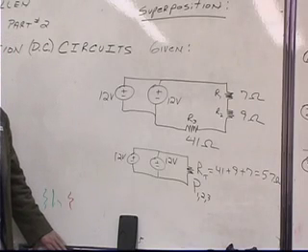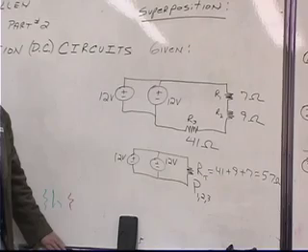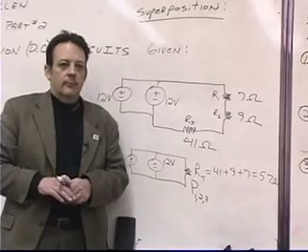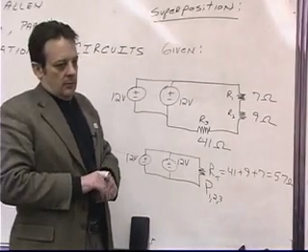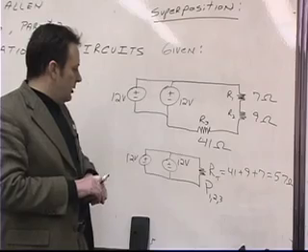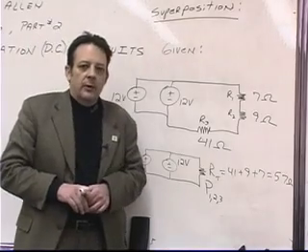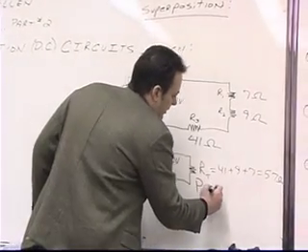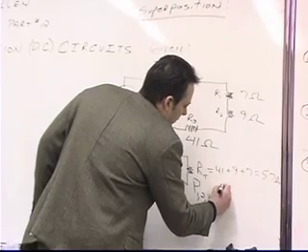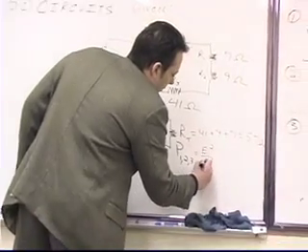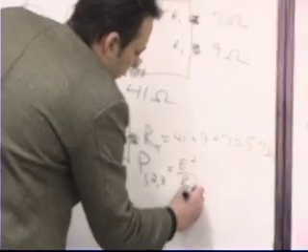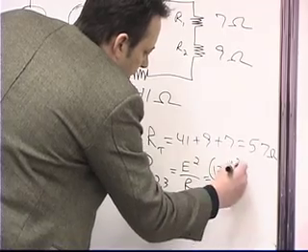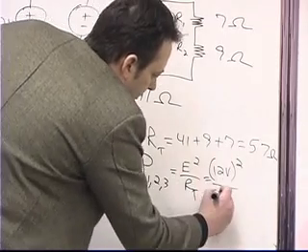what formula would be the easiest and most convenient formula to use? Looking at the Ohm's law wheel. Well, we haven't calculated the current yet. So is there a formula that doesn't, E squared over R would be easier probably, yeah, because then we wouldn't have to calculate the current. So if we calculated E squared divided by R total, then that would be equal to 12 volts quantity squared divided by 57 ohms.